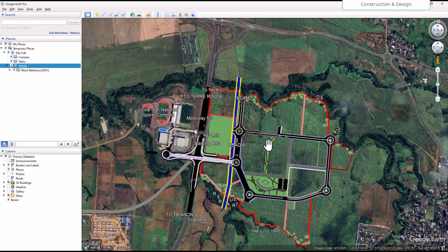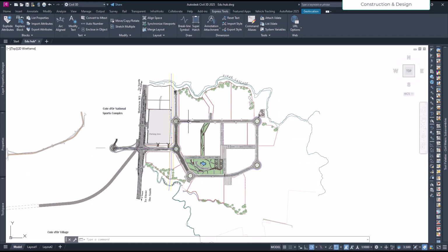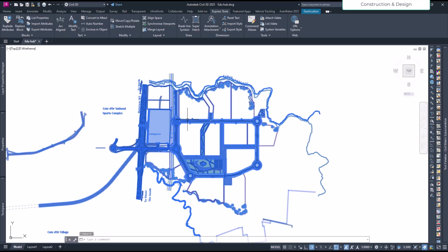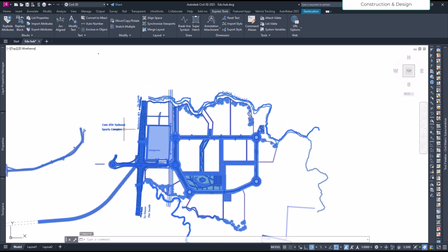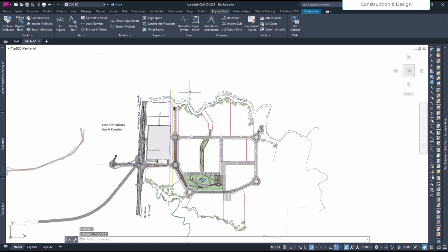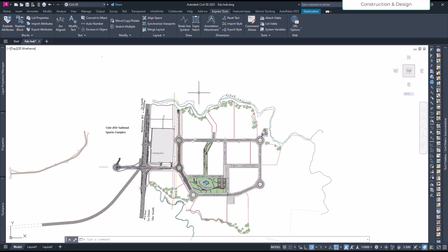So go to your drawing. Okay, we are in the drawing. For that, I will create another text. The text we have here we would have to explode, so let's not explode this. We create another text. I will show you how you can actually put the text and drape it on the map. And remember this: there are certain types of text only, certain fonts, that you can use for this purpose. Other fonts you cannot.